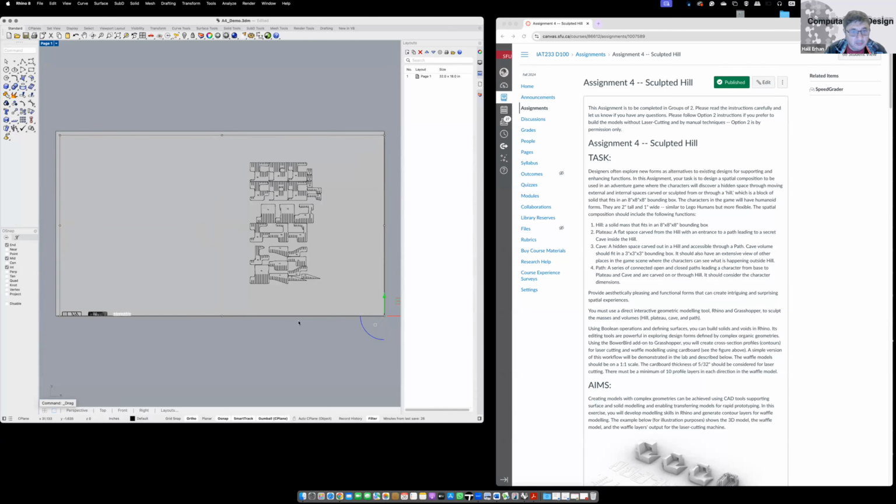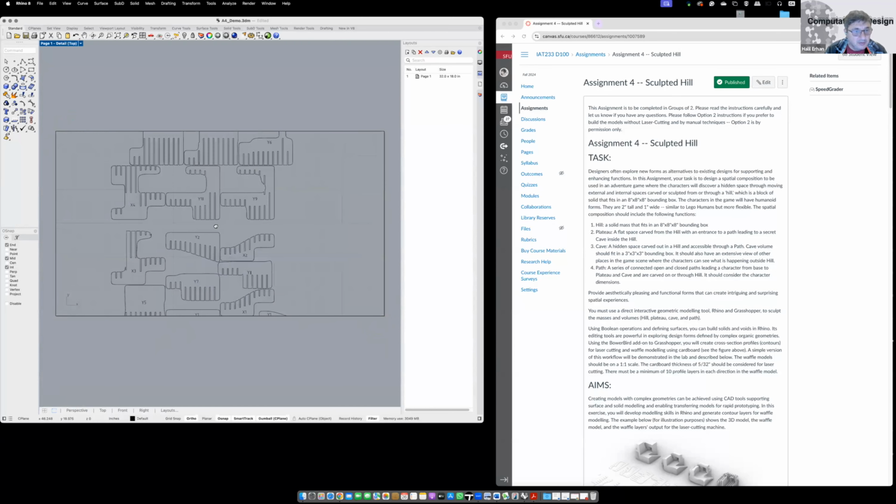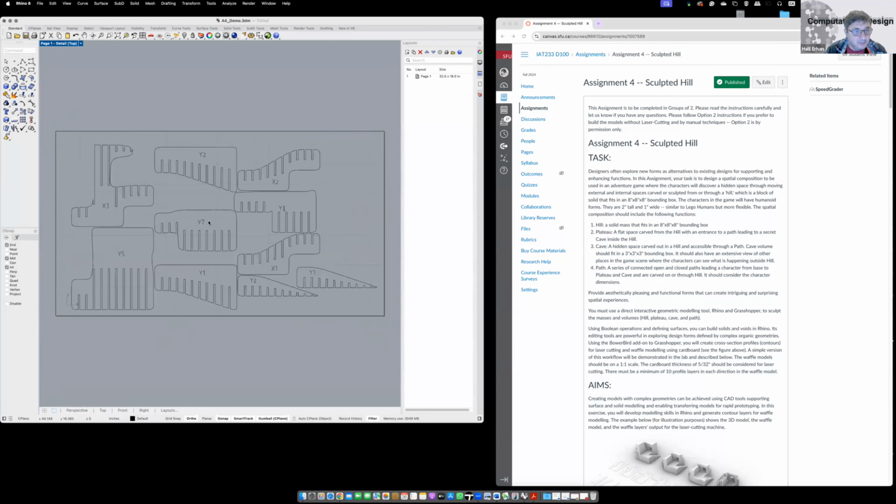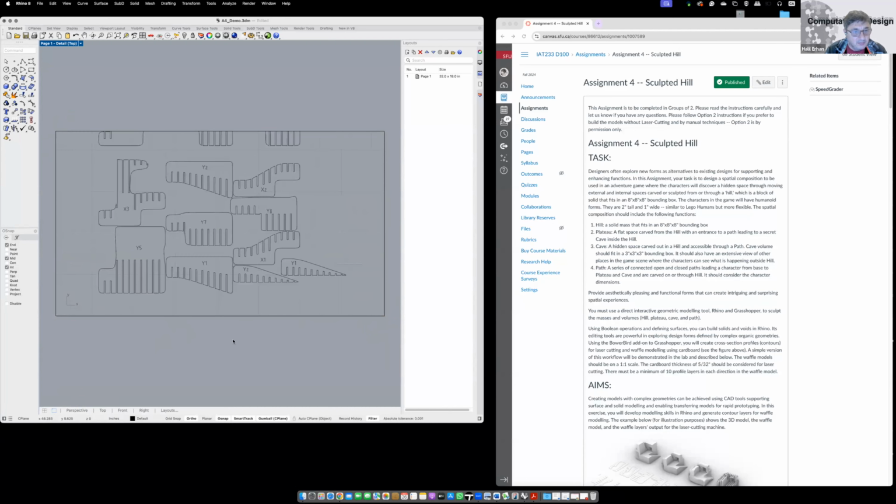I'm going to set this to be full page view. Viewport will be equal to those. And next, I will set the scale. Double click, bring it as close as possible. Put like this. Notice that this is not the right scale. You need to set it to the right scale.